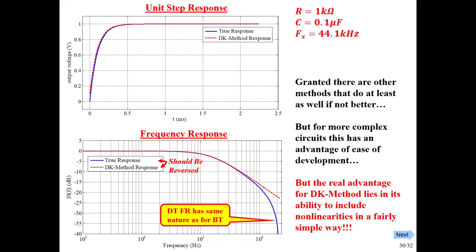Now, if this is bothering you, upsample by a factor of 2, and you'll be able to get all the way up to 20 kilohertz virtually perfectly. Then you have to downsample back down before you send it out. But that's the idea, and it works really, really well. So there is the way to simulate or model or emulate a continuous time linear filter using discrete time ideas. And it's very, very systematic.